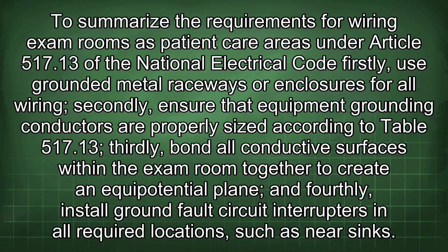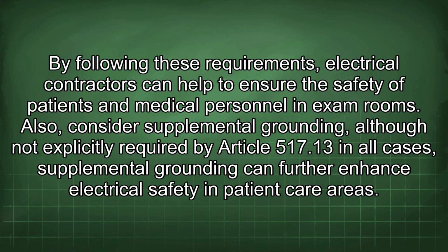And fourthly, install ground fault circuit interrupters in all required locations, such as near sinks. By following these requirements, electrical contractors can help to ensure the safety of patients and medical personnel in exam rooms.